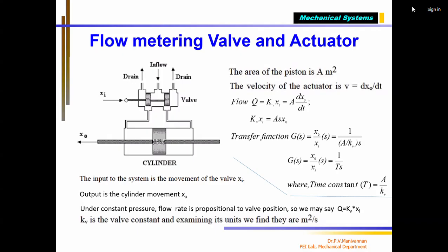While modeling a system, you have to model the valves, you have to model the actuator, you have to model the mechanical system, and you model the control system, and everything can be simulated virtually. You make the entire system virtually, so that in the computer itself you optimize each and every parameter. If you want a particular output, the parameters we are talking about are area and force.